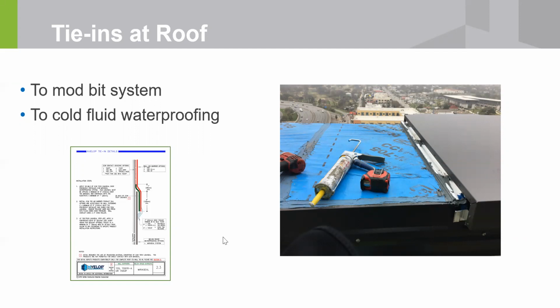It's done under a cover board, or underneath the coping cap, because this blue material at the coping cap, you can't put directly under a black membrane. So you've got to be mindful of the temperature restrictions. Anyway, since Carlisle is also a roofing company, we publish details on how to tie wall stuff into roof stuff the right way.